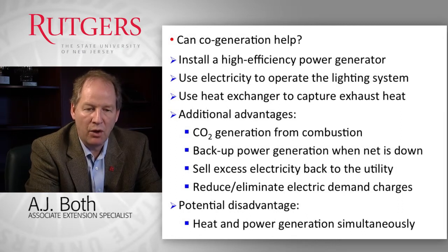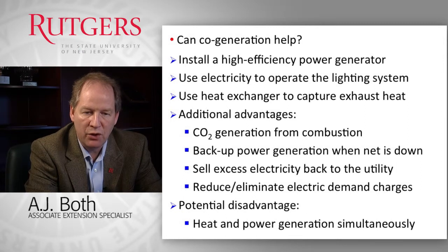And so by having your own power generation system using a cogeneration system, you may be able to reduce or eliminate these demand charges. But one of the potential disadvantages of a cogeneration system is that you always generate electricity and heat at the same time.